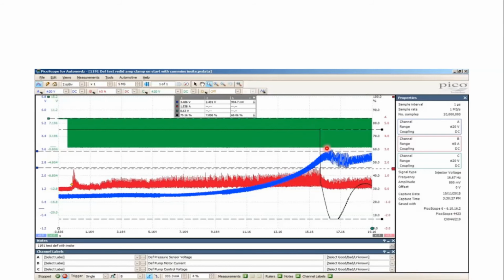So I had good control. The pressure was building. The computer was noticing it, on the scan tool, its pressure. So it thought it was good. The computer thinks that everything is okie dokie, so it drops off duty cycle, and in that process, when the duty cycle is lowered, then your current isn't going to be as high. And that's what's happening here, okay?